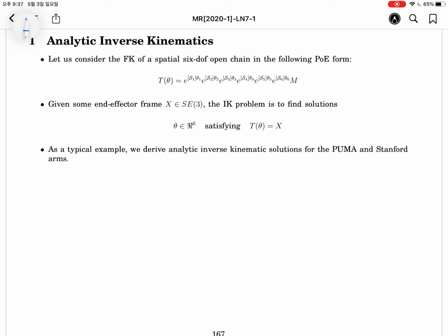As you know, the homogeneous transform has many sines and cosines, so the 16-dimensional 4x4 homogeneous matrix is embedded in a 6-dimensional space. So 10 constraints exist in the homogeneous transform.